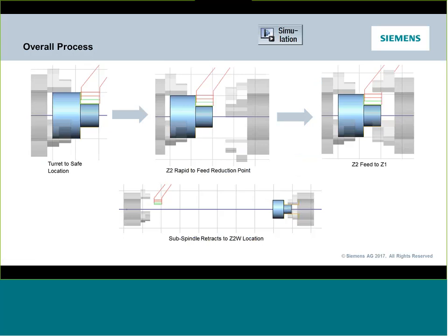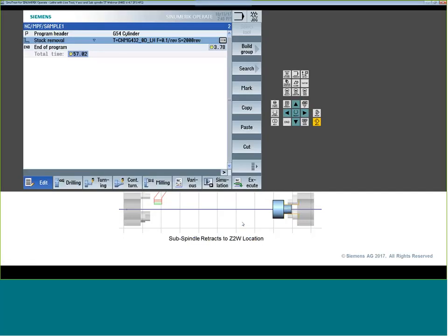Okay, so what is the transfer going to look like? We're going to machine the part. It's going to come over, you see in this second view, to 30 mil in front. Then it's going to move 50 millimeters incrementally till it gets to negative 20 millimeters on the part. Jaws will come down and grab it. And then in our case, main jaws will open, it'll retract back, and then I'll be able to do something on that sub spindle. So let's go make this happen.